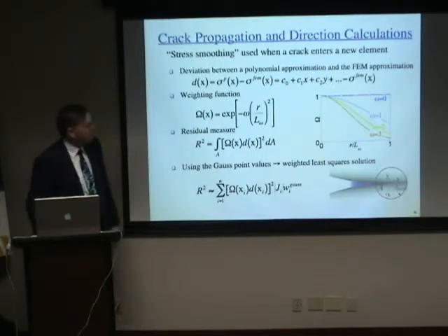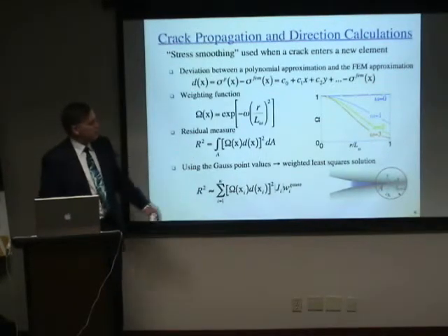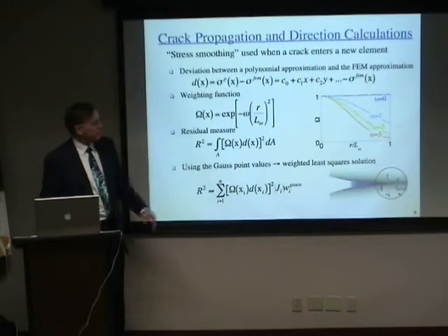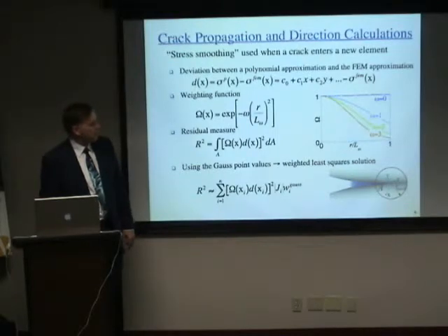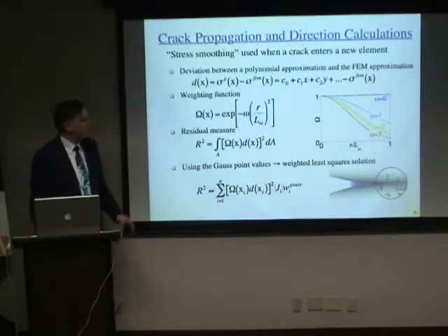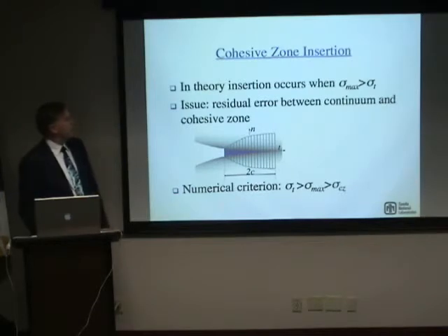Especially for mixed mode, we're going to use a method for smoothing out the crack field. This is something that's quite common in the literature, where we use a neighborhood of Gauss points surrounding the crack tip to come up with a polynomial representation. And for time's sake, I won't go through that.